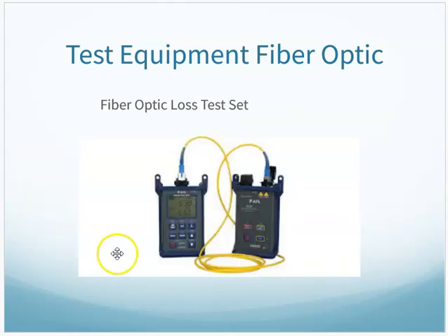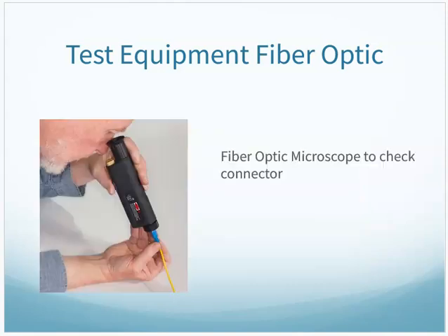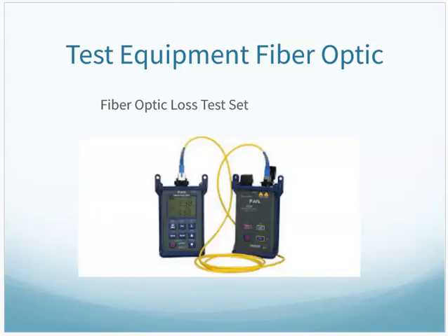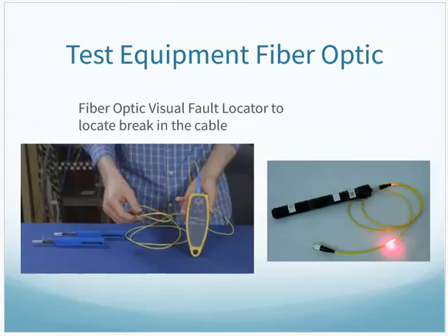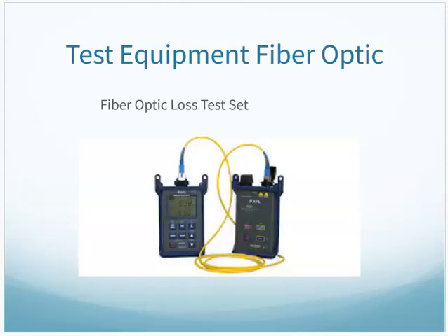One of the last tests we'll do is a loss test. We'll look at how much signal loss is across the fiber. And as long as there's not much, the fiber link is good. If there's too much, then we know there are going to be issues with that fiber link. That's pretty much the testing we do on fiber. And I have meters to test all these so we can try them out and see what the end of the cable looks like, where the fault might be, and if there's signal loss on the cable. So there's the last of the terminology from Chapter 2.